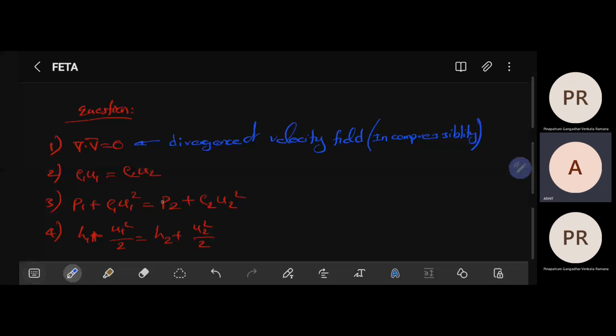Okay, sir. But if del rho by del t is 0, then it can also be shown as a representation of incompressible flow. Yes, that is the constant density flow. That is capital D rho by capital D t equals 0. But del dot v bar equals 0 is your incompressibility. Just revise these basics, and you will get much more clarity on why I'm stating it like this.